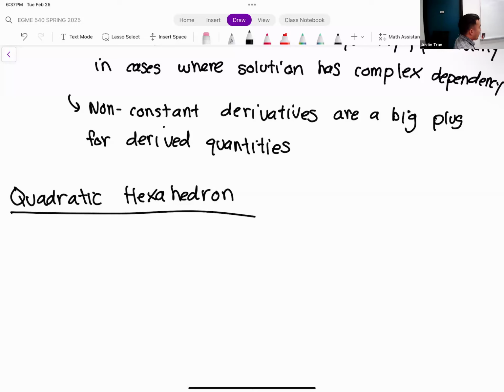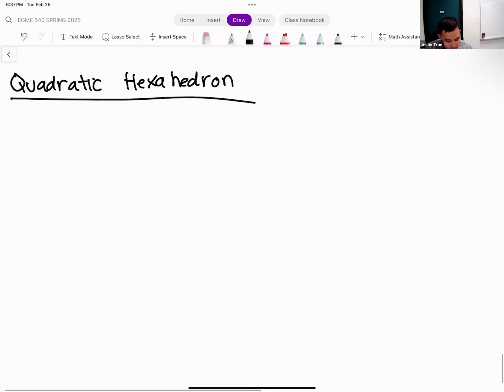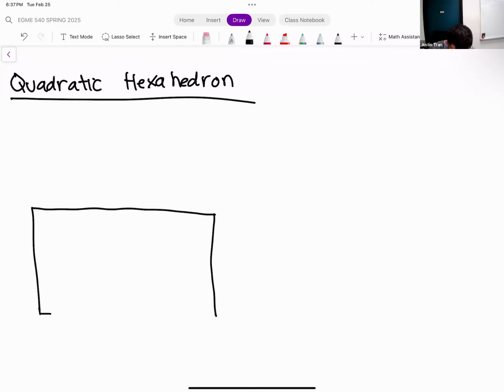Okay, so the way that we're going to derive the quadratic hexahedron is the same as we've derived all quadratic elements, and so we're going to add a mid node to every edge of the hexahedron. And the hexahedron has a lot of edges, so I'm probably going to miss 1 or 2. So hopefully it all adds up to 20. It should add up to 20. But we'll see if my geometry and my hunger...